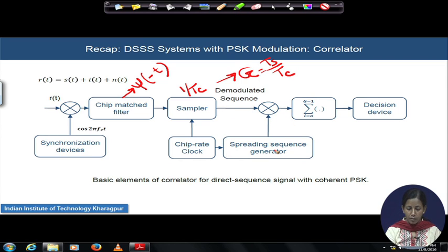This demodulated sequence at the output of the sampler is multiplied with the locally generated spreading sequence, and we saw earlier that this generates the chips, which are called Zi after multiplication. This multiplication combined with the adder jointly offers the respreading operation in the receiver, and it is a correlator based architecture as a whole.